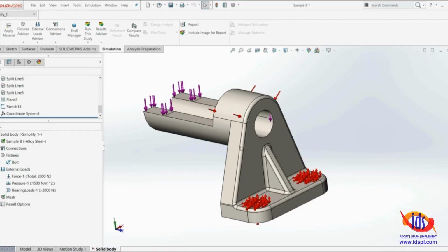So basically, in finite element analysis, discretization is a critical process in which continuous CAD geometry is divided into smaller elements, but the shape of the elements decides what kind of mesh we create. So we need to create a proper mesh to get proper results. We also have to be careful what kind of mesh we create, because the shape of the element affects the final result: stresses, displacement and strain. And if we have a distorted element, then our result will be inaccurate as well.